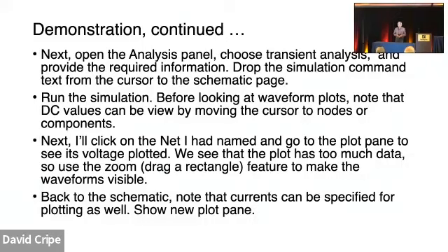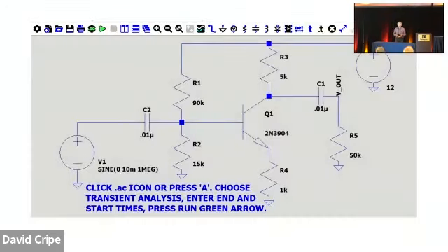When we do the analysis, I'll show the voltage, and then I'll want to show that you can also plot currents. So I'll move back to the schematic and put the cursor over the load resistor. It'll plot the current. Then at that point, I want to show you how you can add a separate plot plane. These plots are going to end up on top of each other. So right-click, choose New Plot Plane. It's going to give a split screen. And then I go, well, I better wait till I get there. I don't want to be talking.